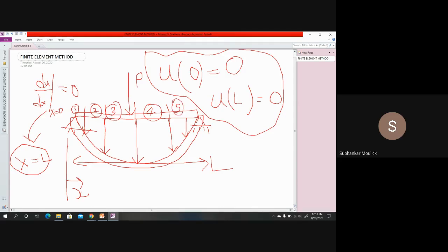Fine. Now, if you plot this deflection curve element by element and then combine it together, you get this kind of curve, somewhat a sinusoidal curve. It cannot be a cubic curve. It cannot be a quadratic curve. Will it be, or not? A cubic or quadratic curve can look like this or like this, but a sinusoidal curve looks like this. It can be a cosine curve, it can also be a sine curve.